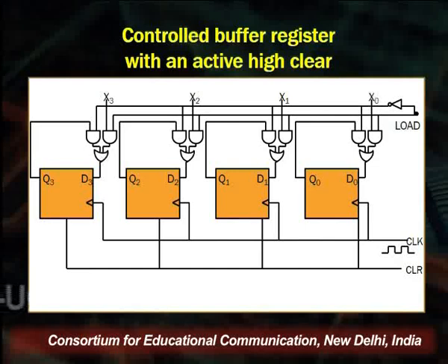If you look at the diagram carefully, we have a 2-input OR gate here, and both the inputs of the OR gate are coming as outputs of two AND gates. Now these two AND gates form a very symmetric structure. In digital electronics, everything is modular. So if you have to increase bits, or increase or decrease processing, we have to remove or add everything in a modular fashion.